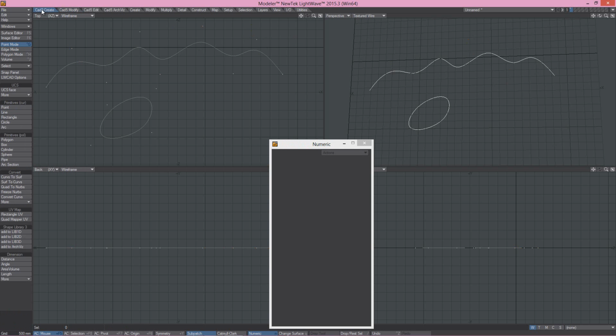We can also cut the new curve type locally. So when I cut here with a point, this curve is divided only locally, so only local control points are modified and the rest of the curve is intact. This is very useful because we don't need to destroy the whole curve, especially when it is such a long curve.